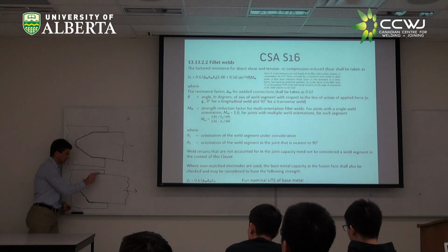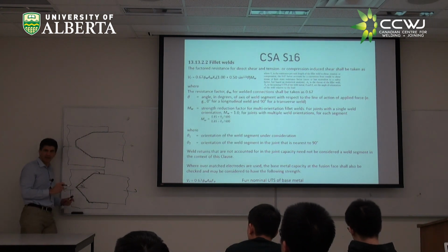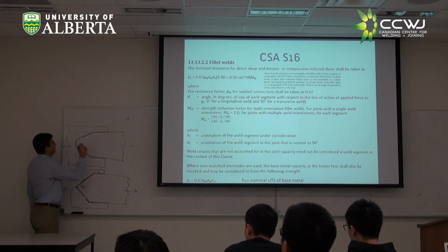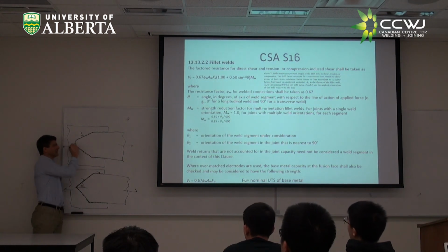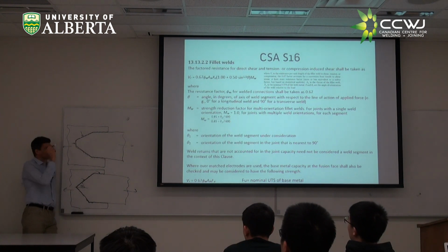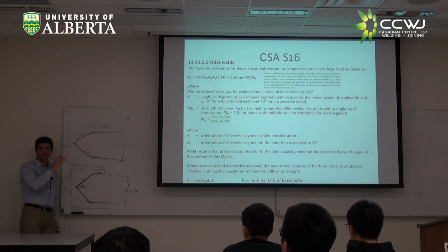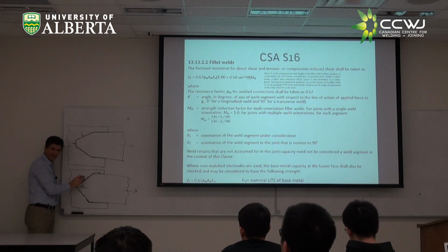How about this? No. Good, okay. Will this one develop full strength? No. Why? Because of this guy here. Now, that's what this formula is taking into account. Although these two welds look much the same, I'll get full credit for this weld here, but not full credit for the weld here, because this will break first.